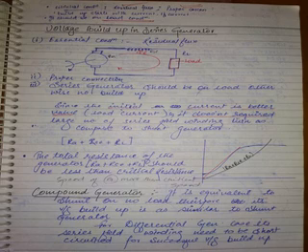Listen, previously in a shunt generator, the initial current is flowing into which winding? The shunt field winding. So you are limiting that. When the initial current flows, the resistance of the shunt field winding should not be more than this value. If the resistance of the field winding is more than that value, the current can't enter and it won't build up voltage. The field winding resistance is playing a vital role there. In this particular machine, when it starts to build up, when you connect some load, the initial current is flowing through which resistance? It is not one resistance here. The current is flowing through RA, through the series field winding, and through the load resistance. You can't break it up now. You can't simply say the resistance of the series field winding should be less than. No. The initial current is flowing through the whole loop. So all the resistance of this loop should be less than the critical resistance.